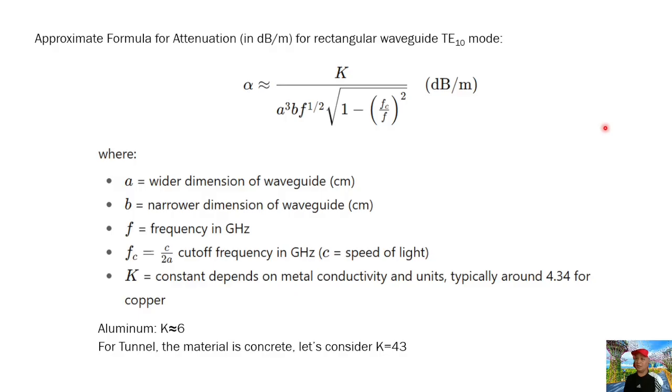So when I joined, I did a calculation. At that time I used a waveguide model to calculate the tunnel loss, and of course I left a lot of margin. The conclusion I gave the team at that time was that it can cover at least 1 kilometer. The team believed me, and they used this to tender for the project, and won. And of course, we installed and implemented this project successfully also.